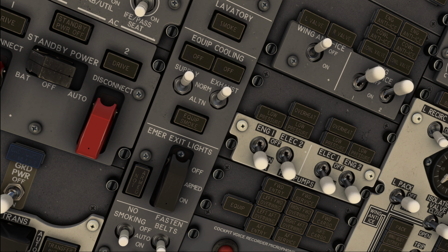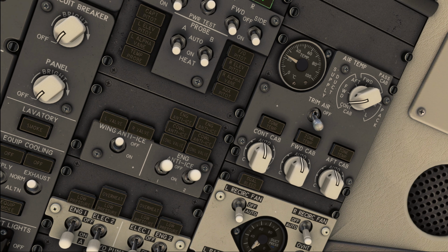Now let's move on to the anti-ice systems, and over here let's start with a little bit of general knowledge. On the 737-800 and the CFM56 engine, bleed air is taken from the 5th and the 9th stage of the engine compressor. On the MAX, this is different. On the LEAP 1B engine that is installed on the MAX, bleed air is now obtained from the 4th and the 10th stage of the compressor. And with that come some changes to the operation and indication of the system in the 737 MAX.